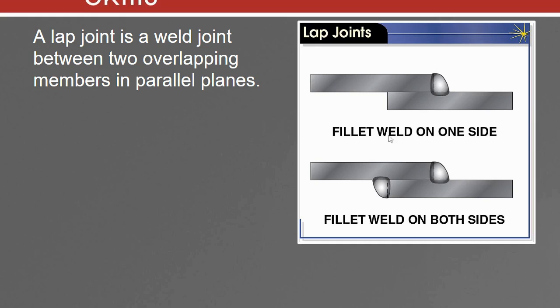If you are having something where the load is going to be pushing down right here in the center, you're going to want welds on both sides. If you're having something where a load is only pushing against this weld, then you're not going to need welds on both sides. But that's going to go with the welding procedure too.